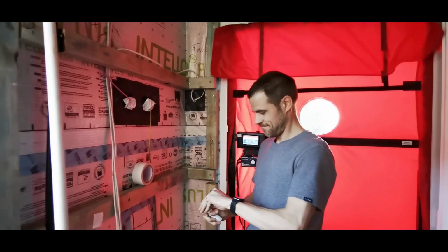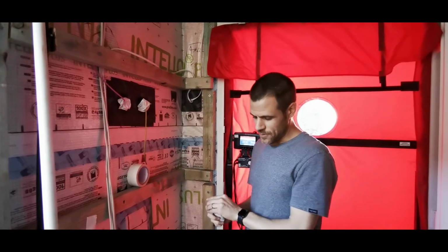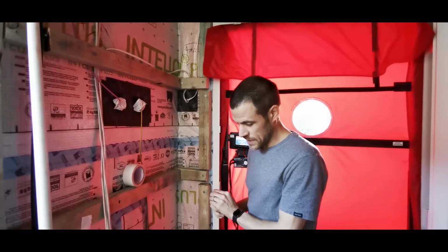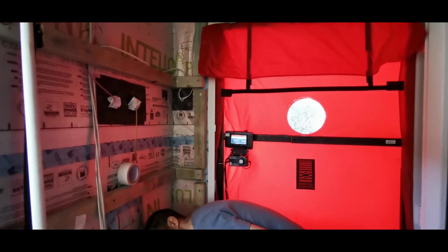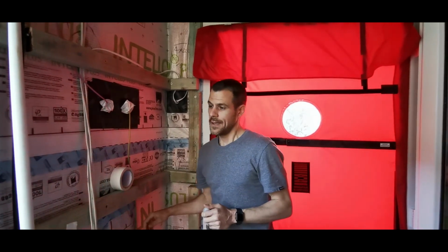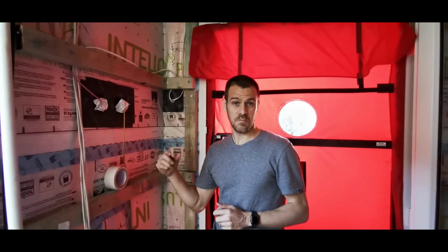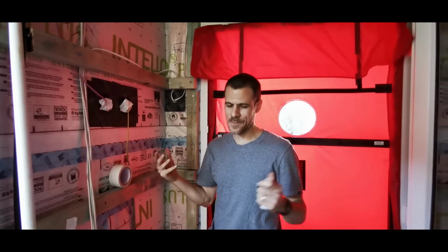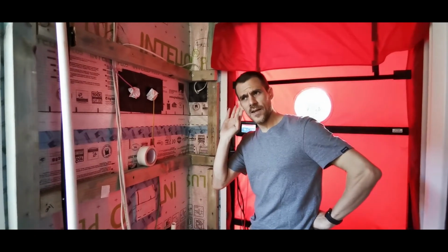It's just a big one. I just hear a noise. What do you think is the noise coming from? You'll hear lots of interesting noises when you're doing a blower door test. It's a whistle, and I'm trying to see where it's coming from. So would you say it's a typical whistle sound from a conduit, or is it a bird flying around, or what do you reckon? It's definitely, because it's constant and it's the same pitch, the pitch will change if the pressure changes. So at a higher pressure, the pitch will go up. At a lower pressure, the pitch will go down. It's a musical instrument. So I'd say that's a tune of 50 pascals.